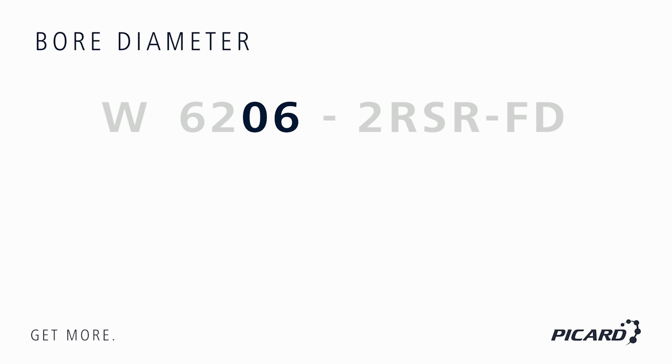Now let's move on to the last two digits in the code. In our example, 06 represents the bore diameter. This means that the inner diameter of the bearing is 30 millimeters. There's a simple rule for calculating bore diameters. If the bore code is 04 or higher, multiply it by 5 to get the actual bore diameter. In our case, 6 times 5 equals 30, meaning the bearing has a 30 millimeter bore.